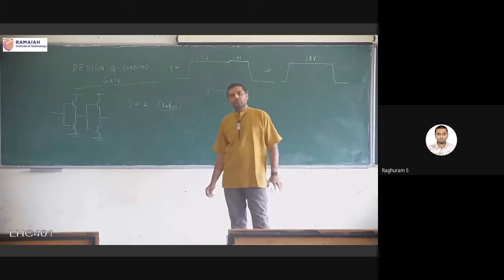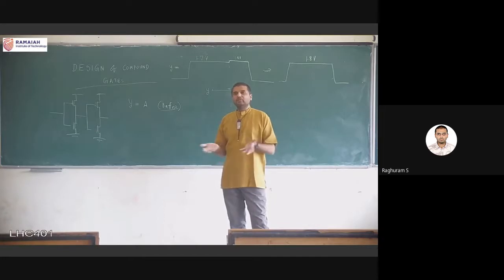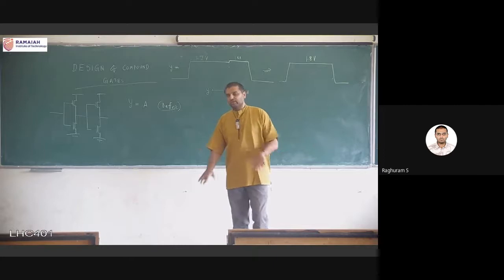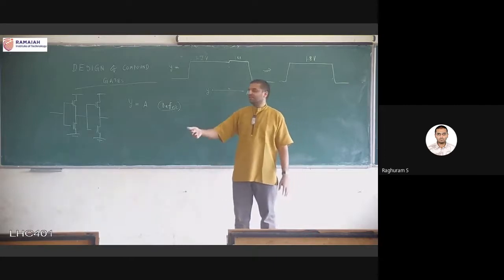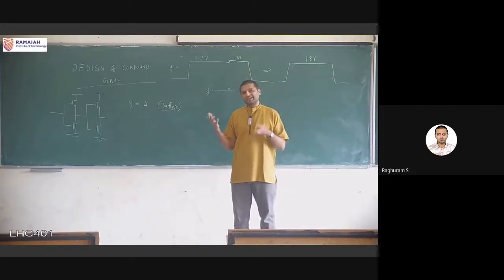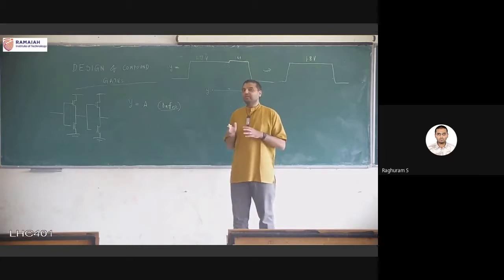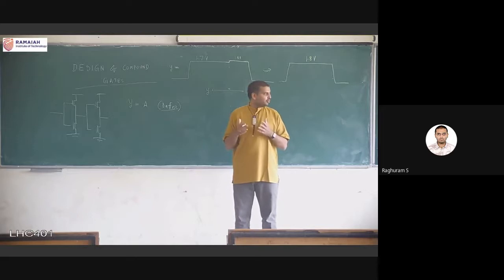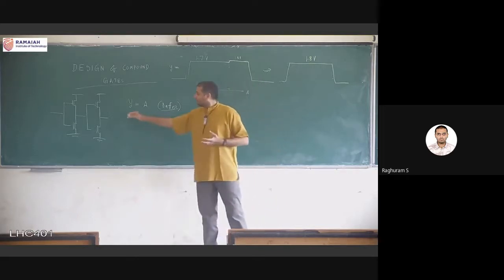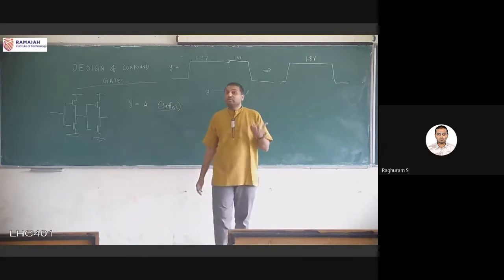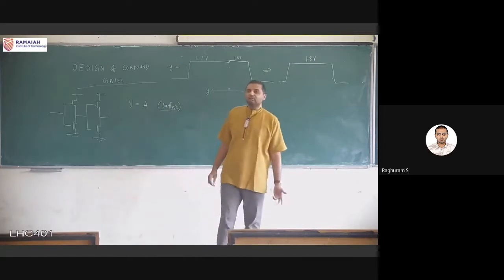One of the most important descriptions I mentioned was physical design. Physical design is responsible for the design at the layout level, and layout is the final step before fabrication. The maximum amount of timing information is available at the layout level, and there if you check and the timing is not being satisfied, you can insert these buffers to improve the timing. So that is another functionality of buffer.